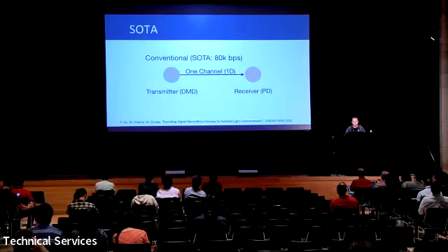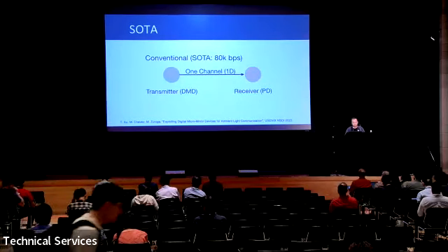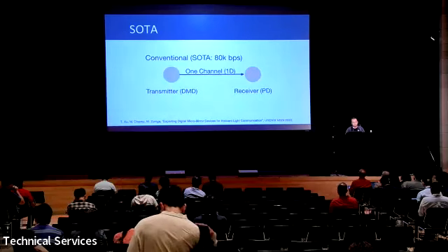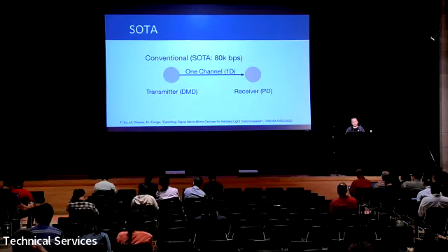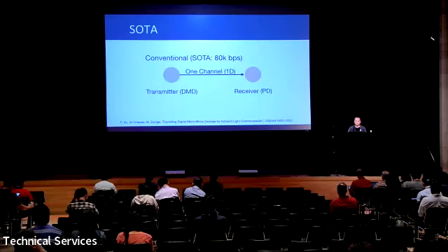There's work which was published in last year's NCDI, and it used the DMD as transmitter and a photodiode as the receiver. It increased the flipping frequency and achieves 80K bits per second. But one thing we should notice in this work is that we do have lots of micro mirrors, right? But all the mirrors are in the same state, all on or off. So it looks like a big mirror.